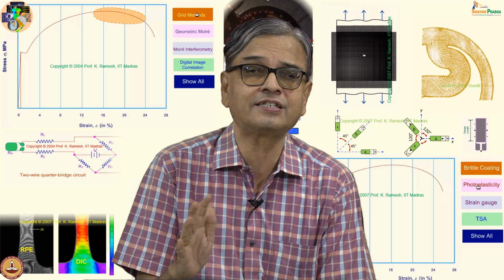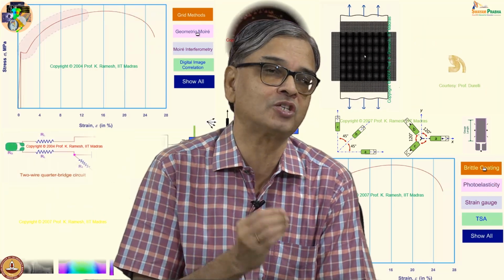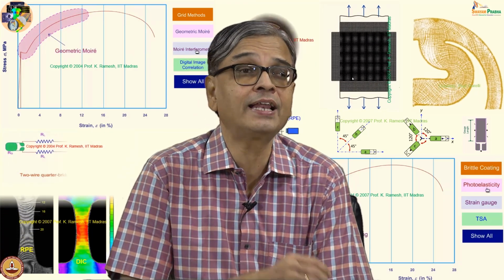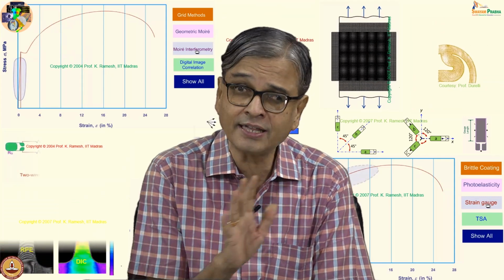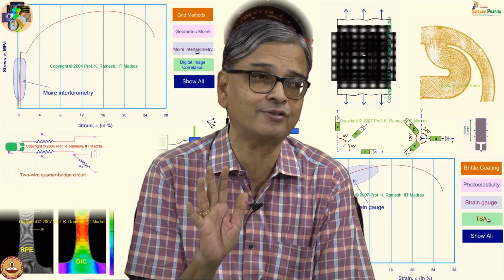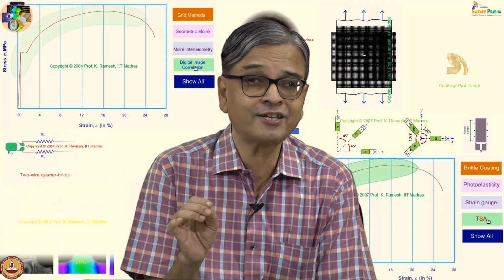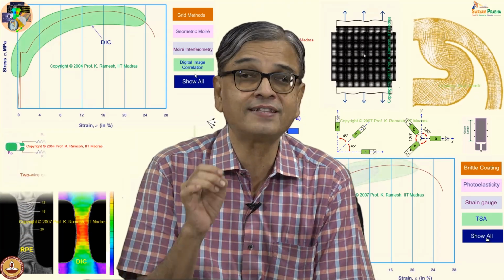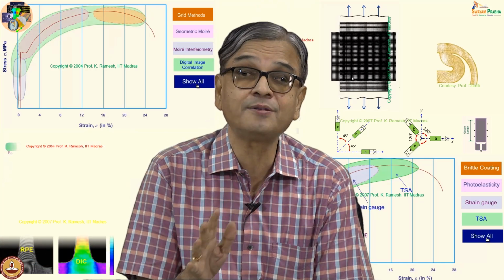As the technology has evolved, finer and finer measurements are possible with strain gauges. With the technology right now, you can confidently measure 1 microstrain. No other strain measurement can give you this accuracy. But if you want to get this accuracy, you have to select the strain gauge properly. You should be sensitive to the heat generation and how the heat is dissipated.